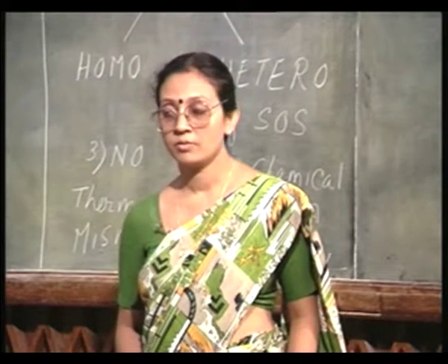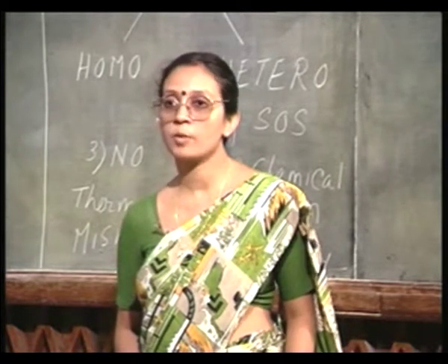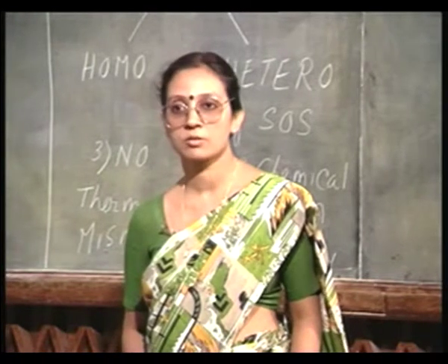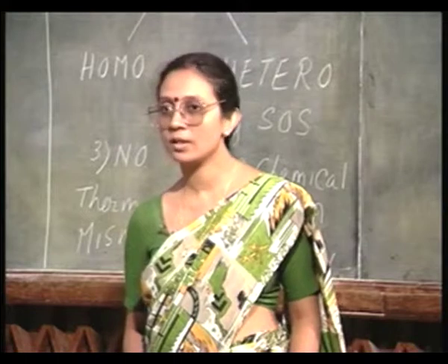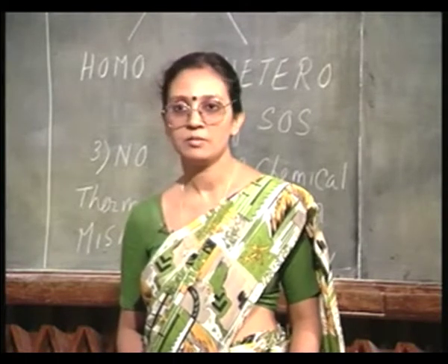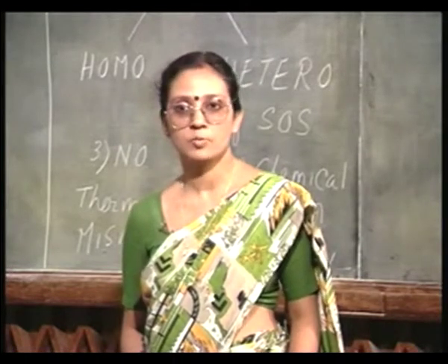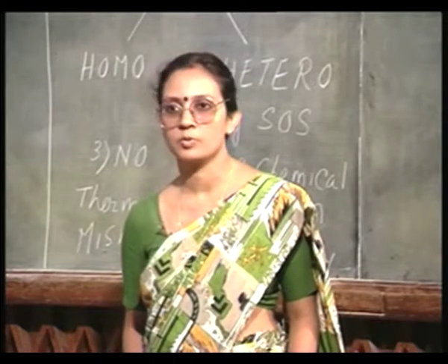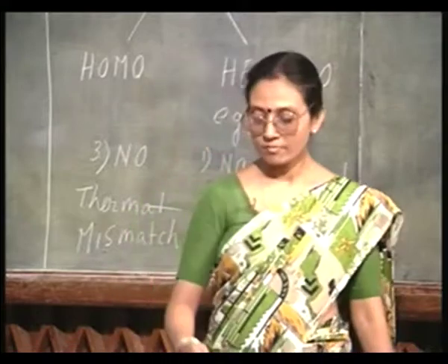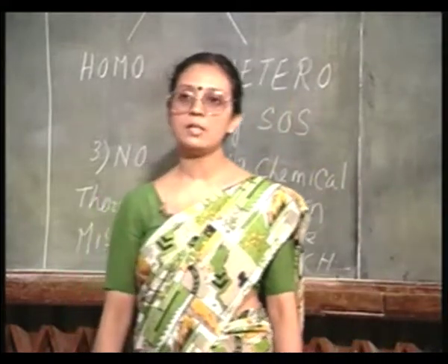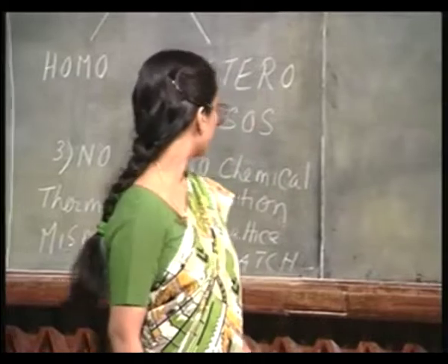Okay. One major problem with gallium arsenide technology is cost. So, if you can use the silicon bulk crystal and grow a thin layer of gallium arsenide on top of that, you have circumvented the cost problem. So, even that is possible to a certain extent today. So, heteroepitaxy is again a very interesting point.